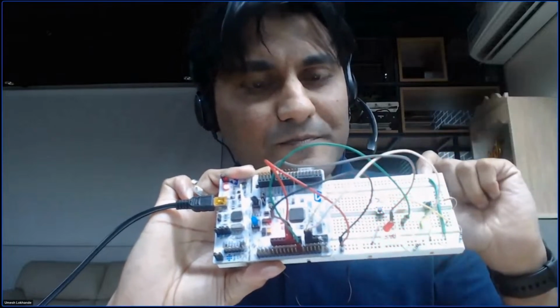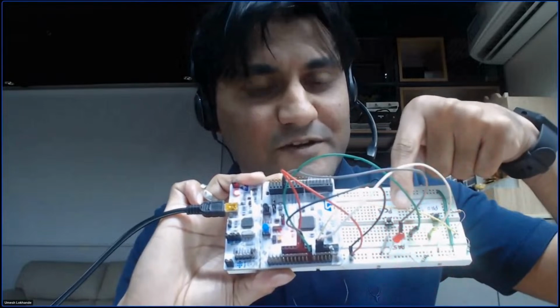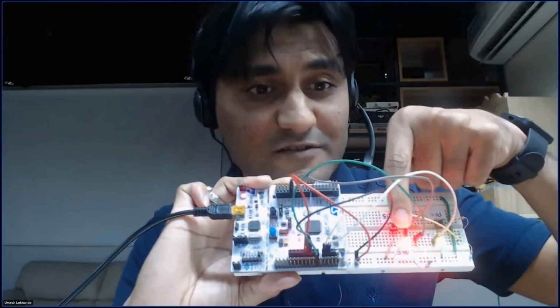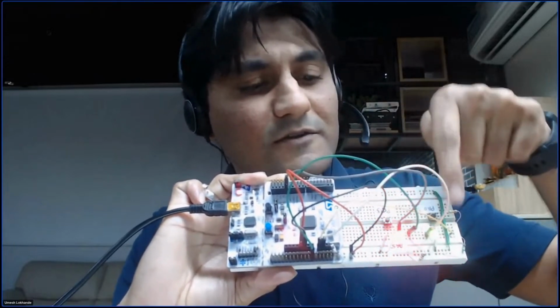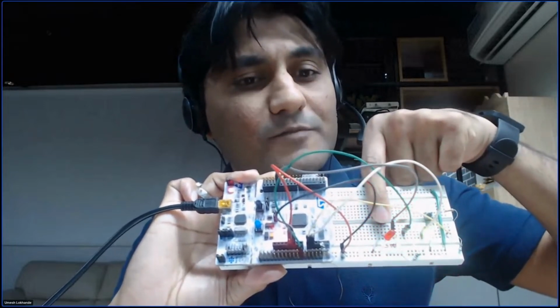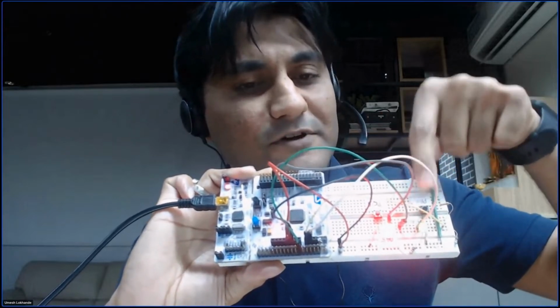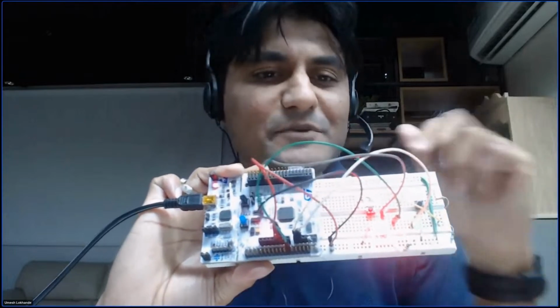Toggling stops. That means this red LED, the second interrupt, has the highest priority. So whenever the high priority interrupt gets serviced, that means when it does what it has to do, then the first interrupt, which has a lower priority, gets stopped. But the moment I stop the high priority interrupt, you can see your first LED starts blinking again, right? Is it amazing? Let me show you one more demo.